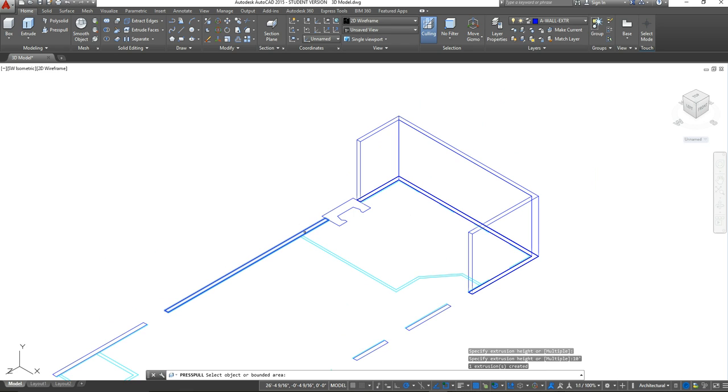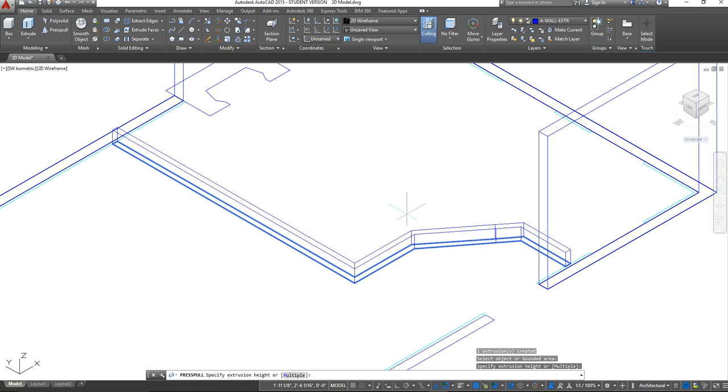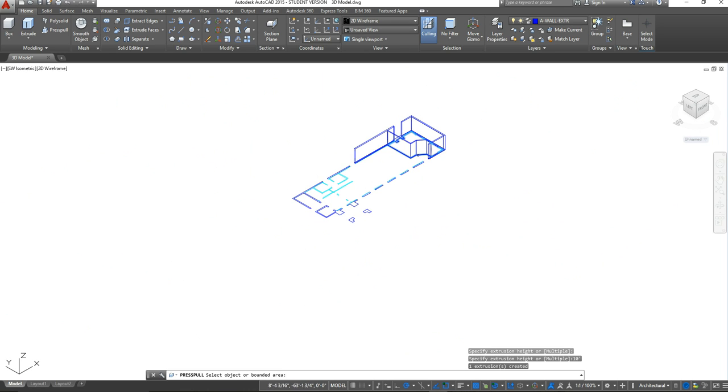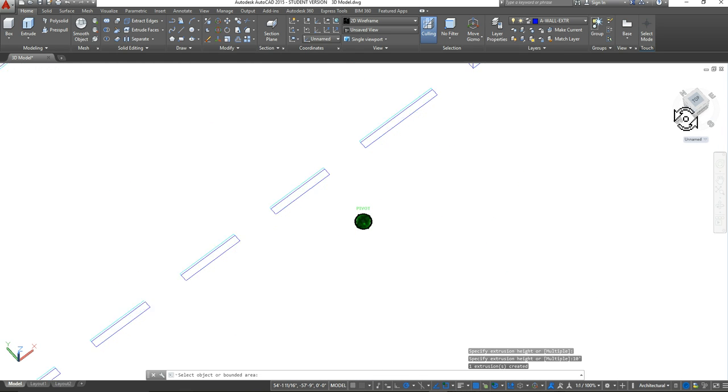since there is a small portion that's a part of the room that I'm creating. So again, I'm just going to hover until I see that whole entire area is selected. I'm going to click one time. That's going to grab that portion for me, and I'm going to type in what I want that distance to be. So I'm just going to type in 10 feet and press enter. I'm going to skip the fireplace for now, and I'm going to do this interior portion here. Again, I'm going to hover, click, drag it up, type in that distance, 10 feet, and press enter. Okay, so you guys can see that it's starting to build up that interior portion for me.